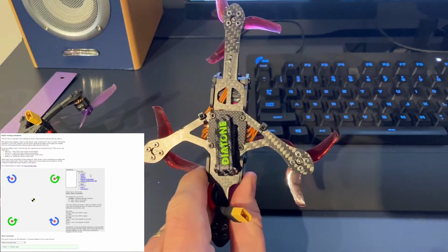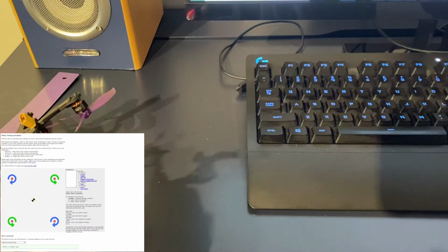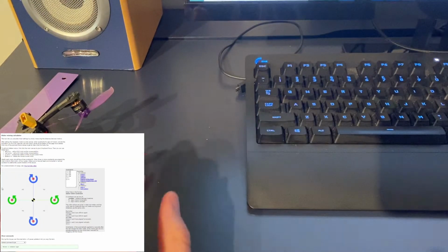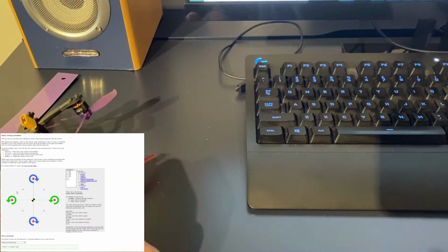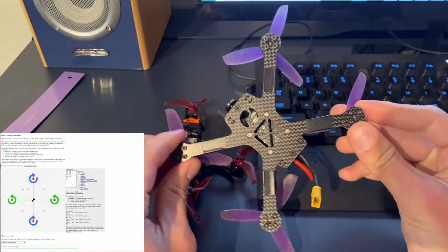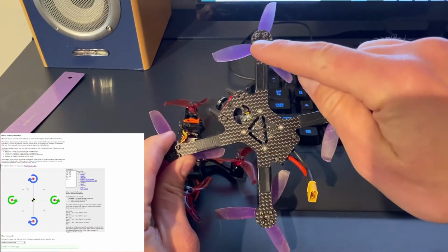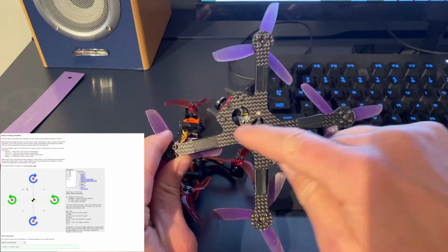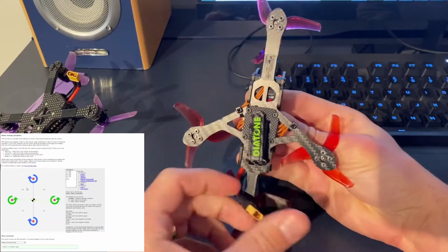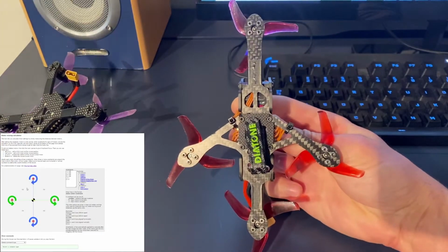In suggestion of that, we'll be using the Motor Mixer calculator. You can see here a Quad Plus configuration to use as a baseline. As you can see here, Motor Mixer calculator is presuming with a Quad Plus configuration drone that you have an equal distance from each motor to the center of the flight controller. In this instance of frame, you can see motors 2 and 3 share an equal distance from the flight controller, but motors 1 and 4 do not.